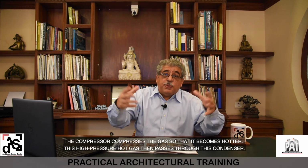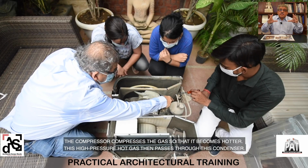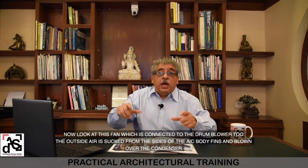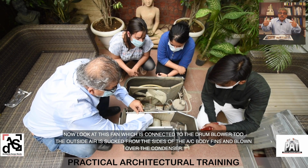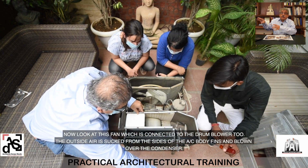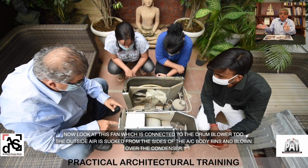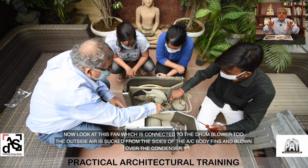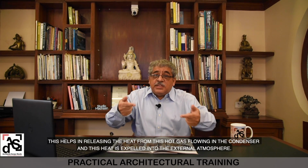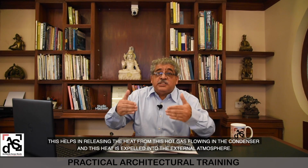The compressor compresses the gas so that it becomes hotter. This high pressure hot gas then passes through this condenser. Now look at this fan which is connected to the drum blower tube. The outside air is sucked from the sides of the AC body, fins which are there, and blown over this condenser. This helps in releasing the heat from this hot gas flowing inside the condenser, and the heat is expelled